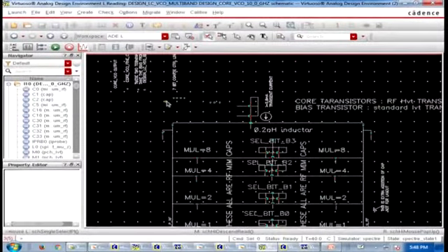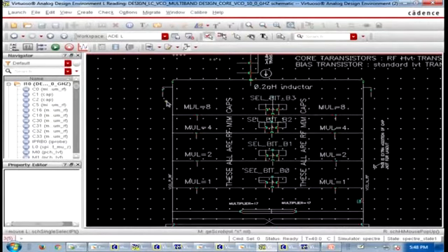What is this in the picture? That is the schematic view of the oscillator. Of course, this is the LC oscillator as already has been discussed, but this is designed for 10 gigahertz in the 65 nanometer TSMC process. A 10 gigahertz oscillator. The application here is a little different.